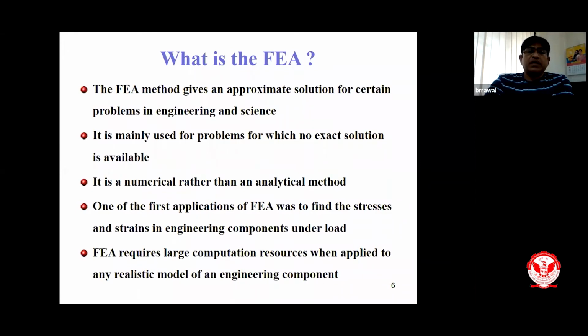Generally, we analyze an engineering problem in three ways. First is the analytical method, second is the numerical method, and third is the experimental method. Analytical methods we use for simpler geometries, and based on the fundamentals of mechanics of solids, we solve those geometries for deformation, stress, and strain.